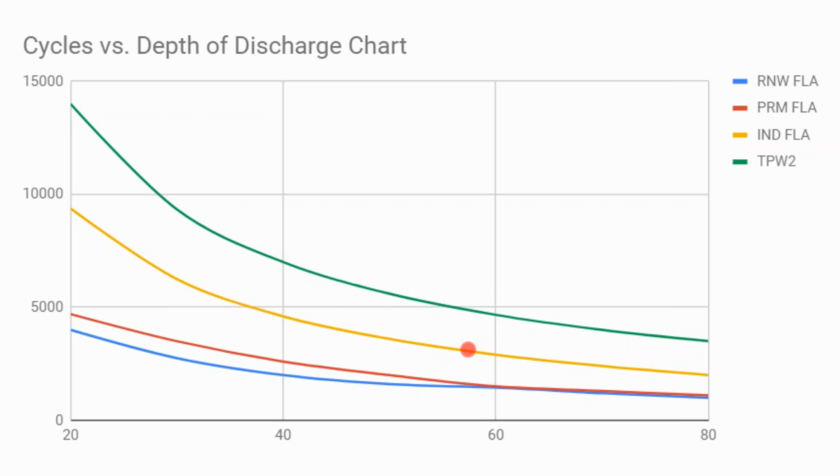And so this forklift manufacturer will take their forklift battery, and instead of having it be a 48-volt shell, they'll put it in a 12-volt shell. So you're basically buying 4 12-volt batteries instead of one 48-volt battery, and it just makes it 1/4 the weight of each individual section, so that you can actually lift it and move it around. But it's a forklift battery in a 12-volt package.